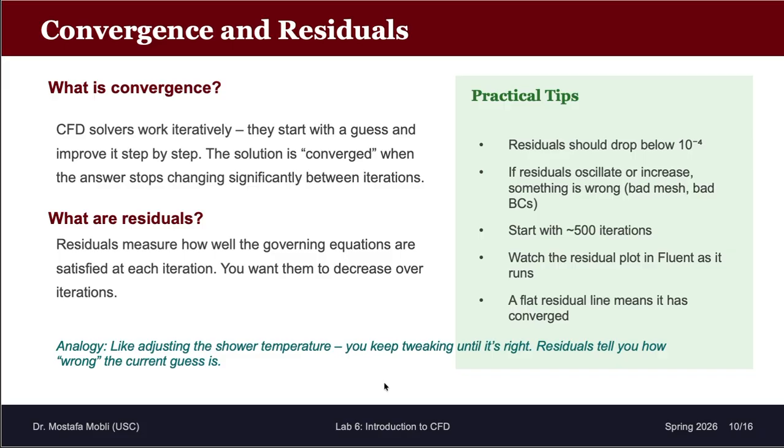So the general idea is your error, which is the difference between the final solution of each iteration and the initial guess of each iteration, becomes smaller than a set value, and you have reached a specific solution. That set value is what we call the residual. Residual essentially is what remains.